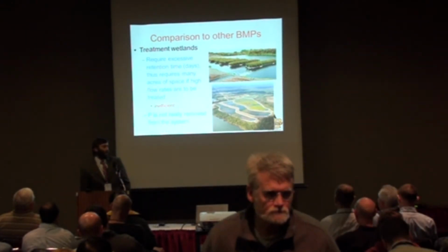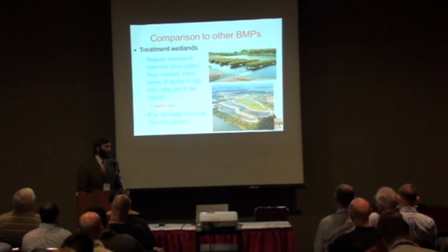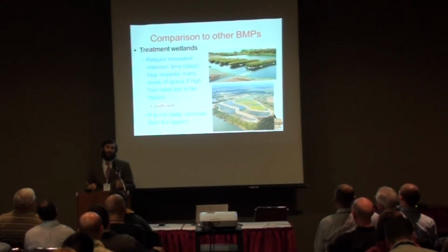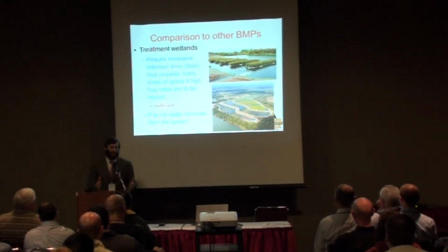Treatment wetlands is another alternative. The issue with treatment wetlands is that they require a very, very long retention time, like a wastewater treatment plant. And long retention time in this type of technology translates to an extremely large area. So with chemical removal being very fast, we're talking much smaller footprints. When you go to wetlands, it can take up a very, very large footprint.